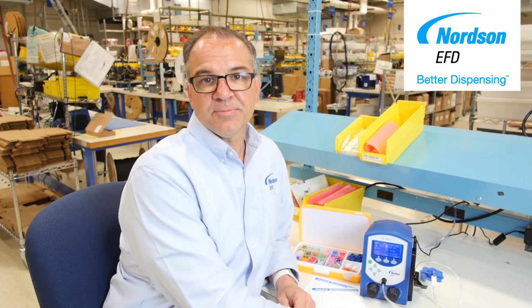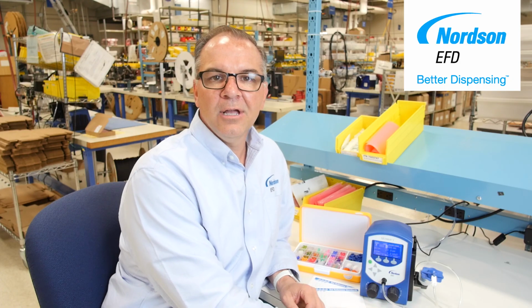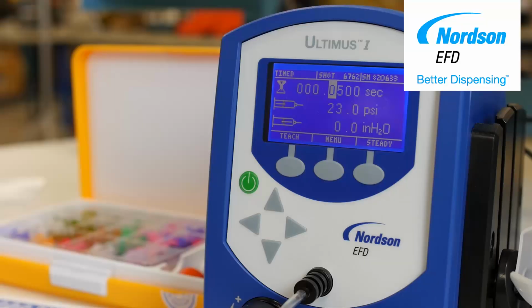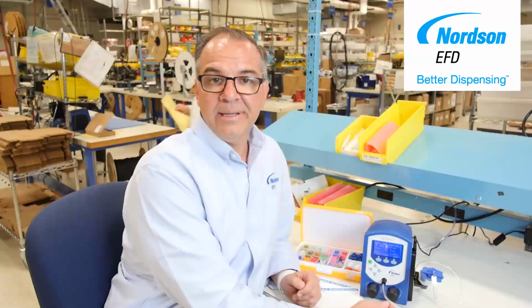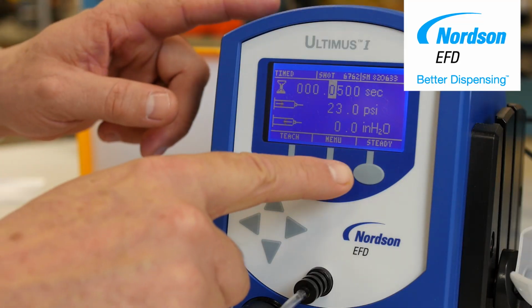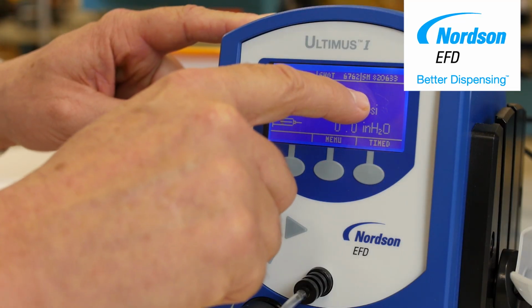So let's talk about the dispense mode. Anytime you want to make a controlled, consistent deposit, you should always be in the timed mode. You'll know you're in the time mode when the time actually displays on the screen. Anytime you want to make a long stripe or a long bead, you should be in the steady mode. Whenever you're in the steady mode, there's no time displayed on the screen.